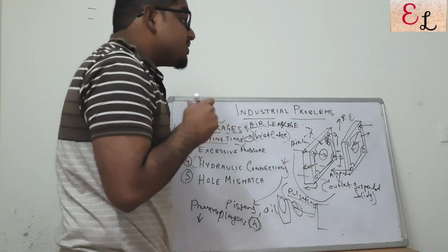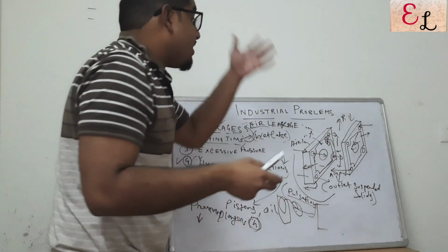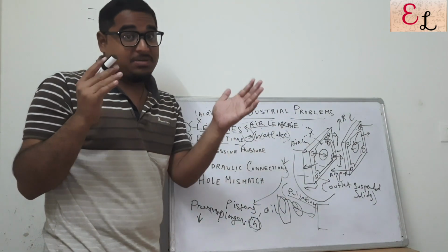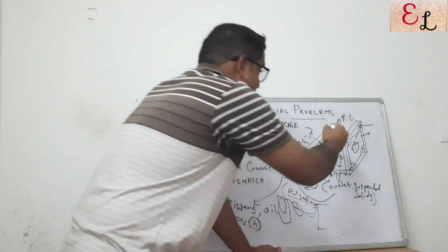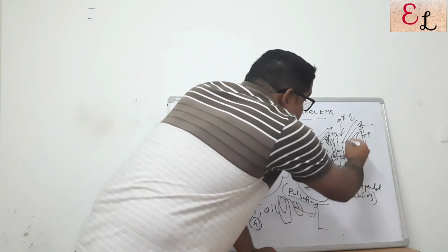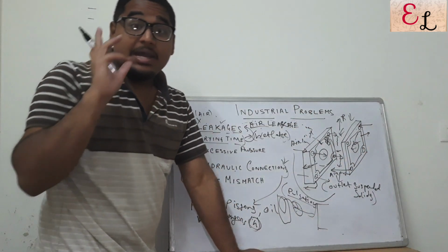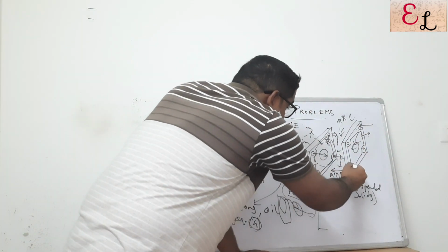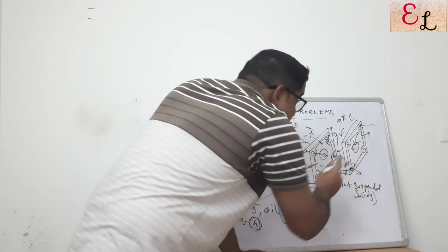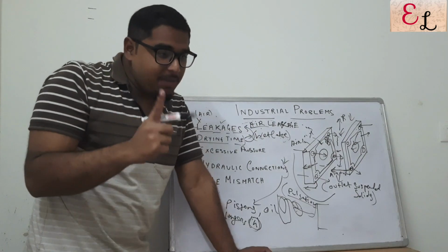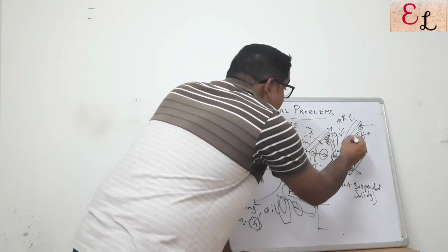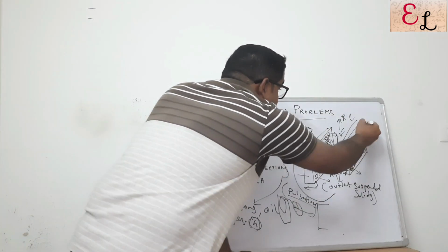Why is it so? Because that lets the air cover the maximum path or the maximum area while circulating in the system. Now the air comes in through the outlet, goes in between the two cloths, circulates through the entire cloth and the cake, dries the cake, and then carries out the moisture with itself and moves out through the hole of the system which is diagonally opposite to itself. But many people, in fact in our industry also, we made this problem of opening this hole and this hole as the outlet hole and this as the inlet hole.